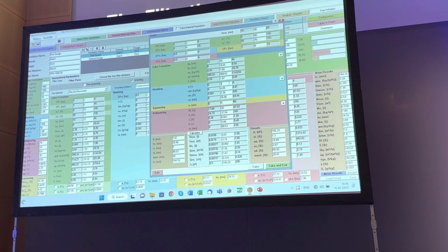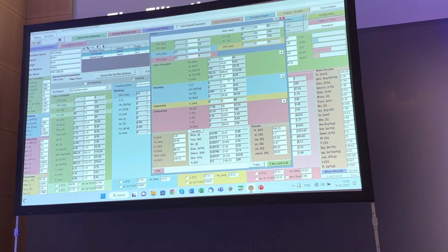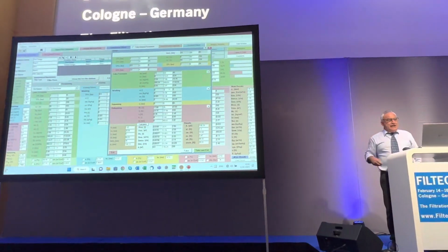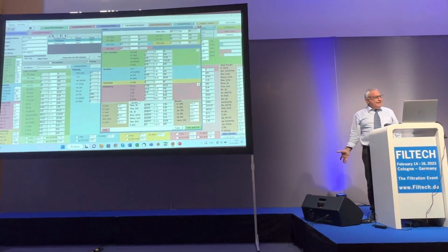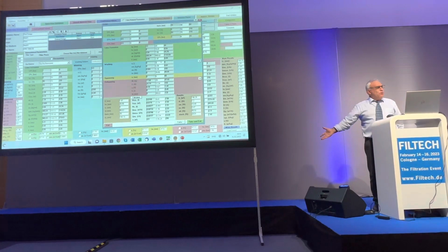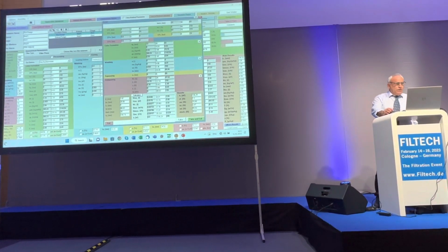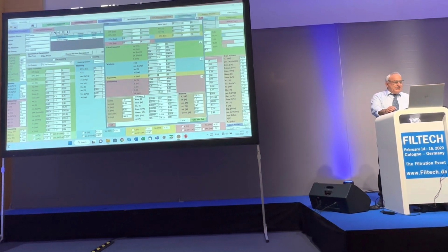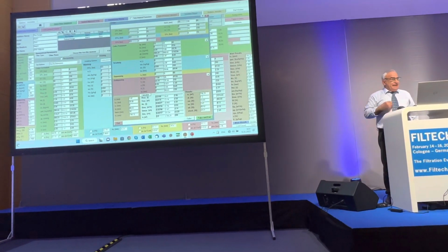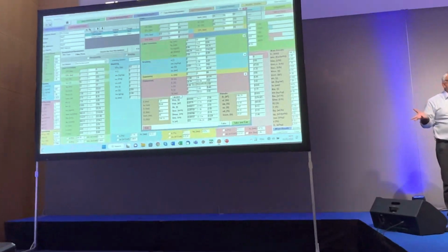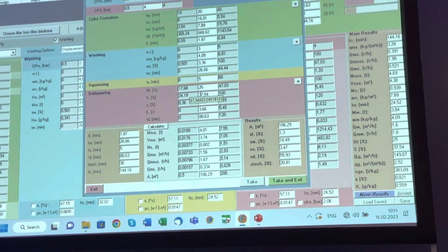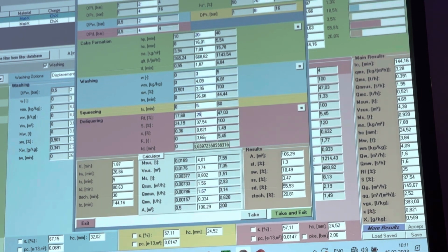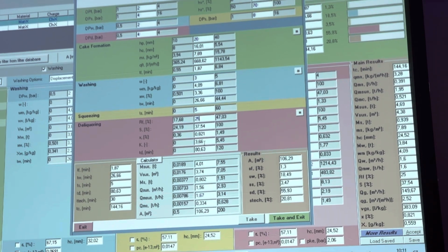So we want to have a good washing, and that is the kinetic parameter. That is the important 3. 3 times the voids of the volume of the cake we use as wash liquid. Yeah? The program here then calculates the squeezing pressure, and then the requested performance, 25% moisture content. To have this, the program calculates automatically the kinetic parameter, the delivery kinetic parameter.